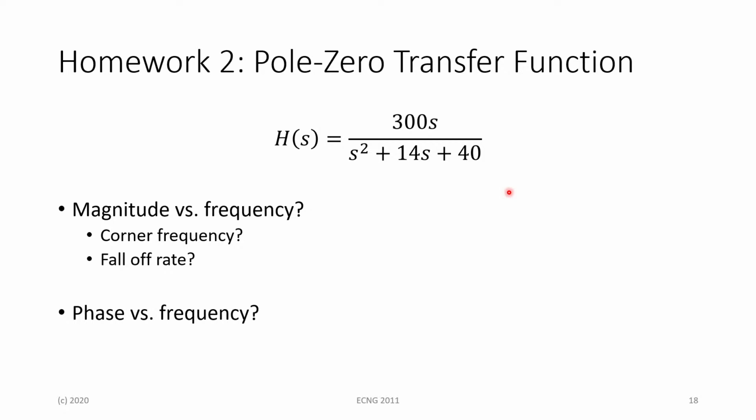What you need to pay particular close attention to is that when you're doing the magnitude plots, for each one of those lines that you're plotting before the poles, in between the poles, and after the poles, please write down the resultant gradients of each one of those lines. As well as for the phase plots, don't forget to write the resultant angle equation. Those actually contribute towards marks throughout the entire question.